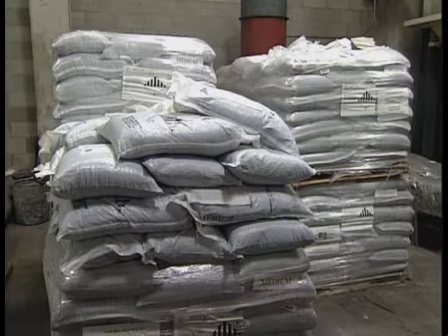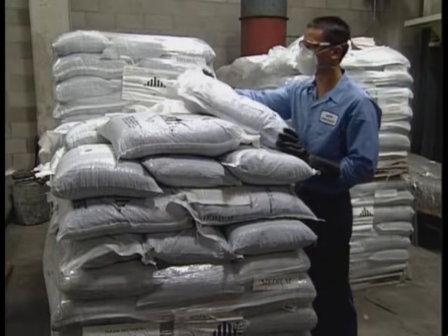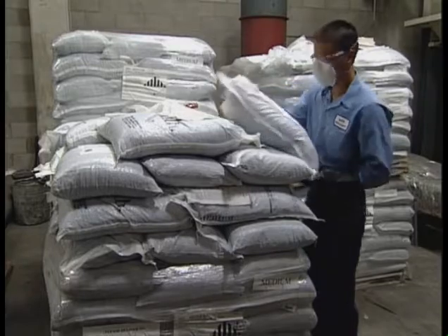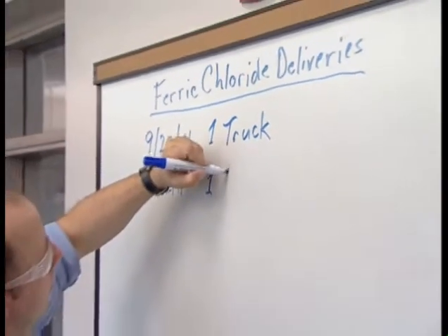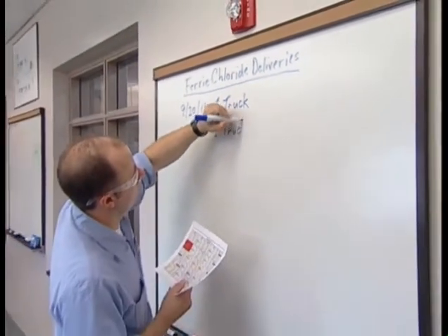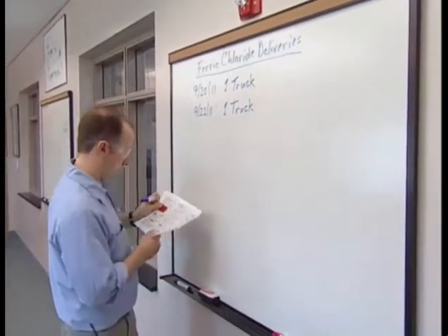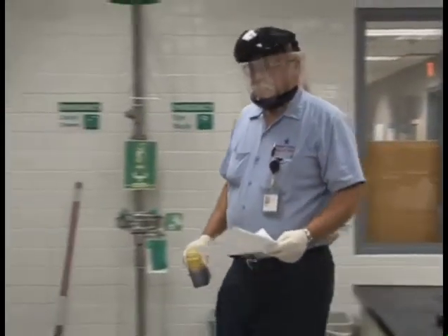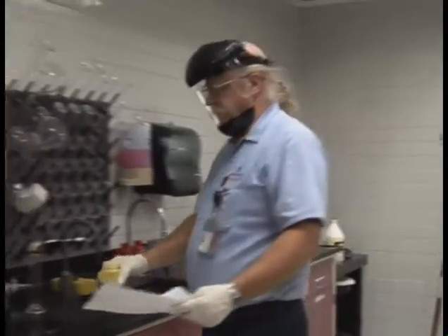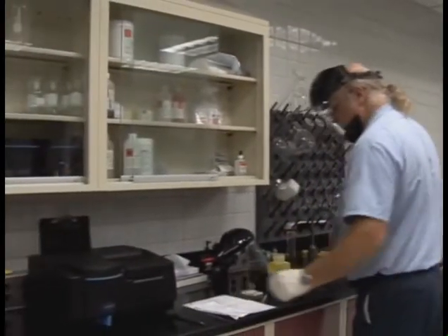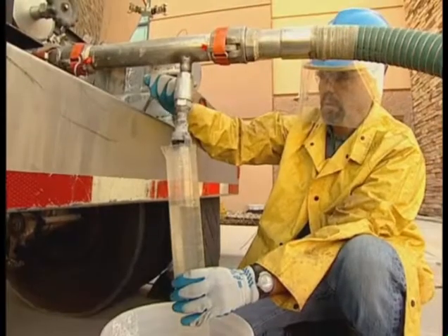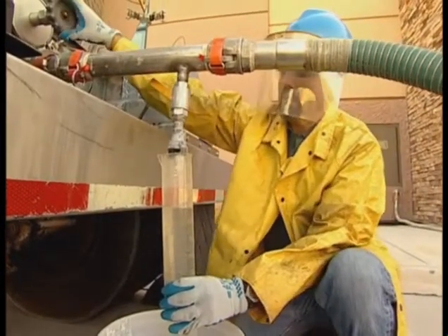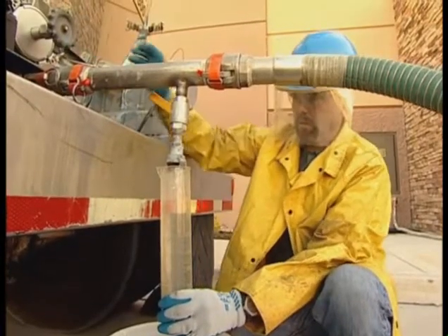Because some state regulatory agencies require certified chemicals, be sure and check with your regulatory authority to make sure you are in compliance. Include in your purchasing and bid documents the hours and days of the week qualified employees are available to receive the shipments. Make sure to include enough unloading time in the schedule so samples can be provided and testing completed. Require a load-specific certificate of analysis. Clearly identify who will be responsible for getting a sample of the shipment: delivery driver or plant employee.